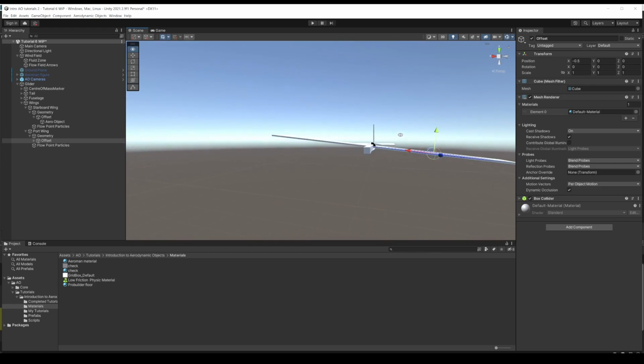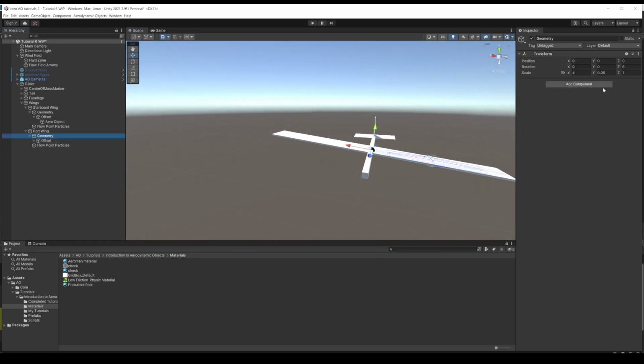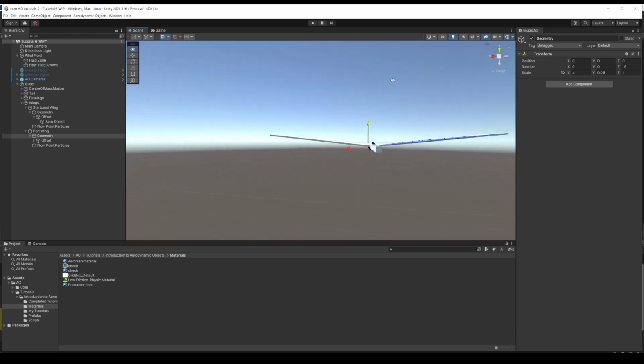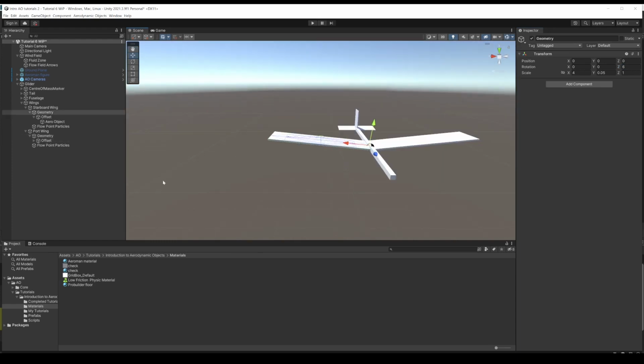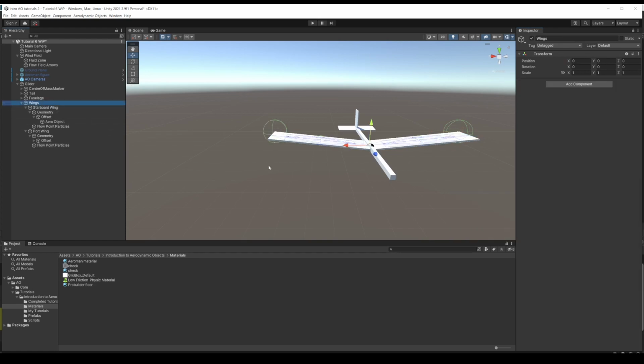The dihedral is symmetric there, so we want to make it anti-symmetric, so let's change that to -6 there. And we also need to transfer across the point particles, so they've been left in the same place. Once again, because we're smart and lazy, let's just change the sign of that and it'll go across the other side. So let's just check everything now.